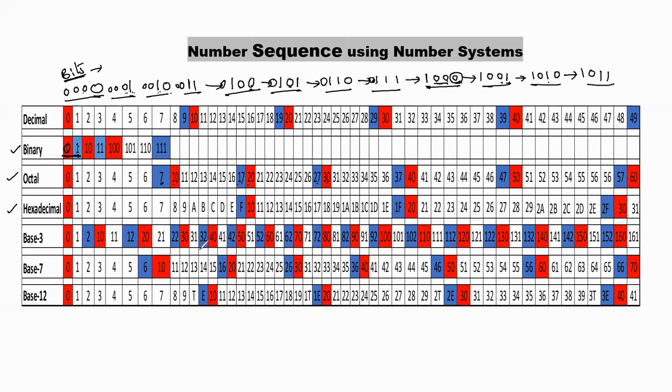Now, with the help of hexadecimal also, here 0 to 9 and A to F are the hexadecimal digits. After F is finished, we have to start with 10 to 1F. The reason is we have to place the leftmost position as 1 and towards the right side, we have to fill all these hexadecimal digits 0 to F. After 1F is finished, we have to replace the leftmost 1 with 2, again 20 to 2F. After that 30 to 3F. Like this, we have to write any bigger sequence with the hexadecimal number system.